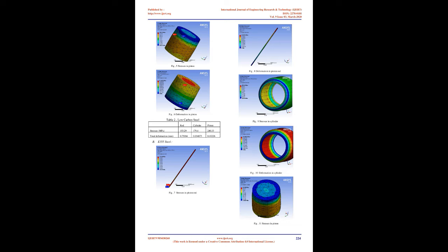P equals cylinder force * factor of safety equals 43,664*3 equals 130992 N. 130,992 equals π²*210*10^9*I / (1.135²*0.7²), so I equals 39.894*10^-9 m⁴. πD⁴/64 equals 39.894*10^-9, so D equals 15 mm. From the BAME Hydraulics Corporation Catalog of Metric Rod Wipers and Piston Seals, the nearest standard rod seal diameter is 20 mm.